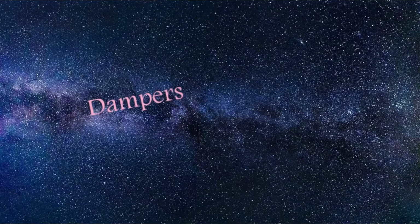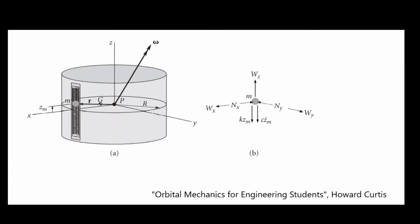We usually don't use a single type of attitude actuator alone. A damper is another actuator usually used in combination with others for a complete system. A damper is a device that changes angular momentum by absorbing energy. Attitude dampers use friction or other means to convert angular momentum energy into other forms.